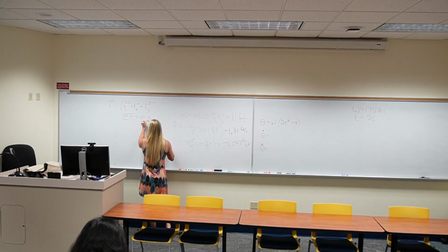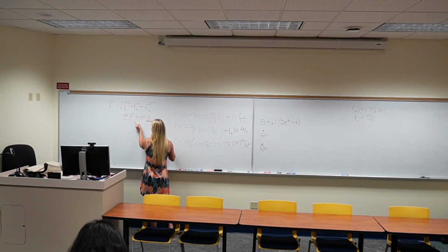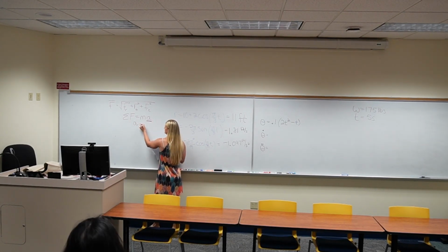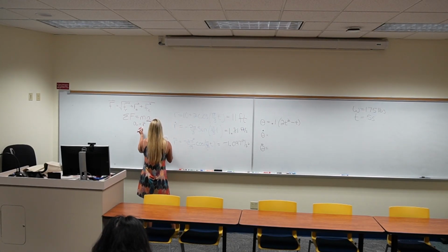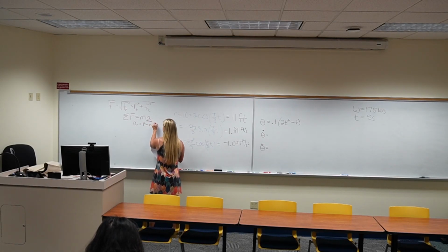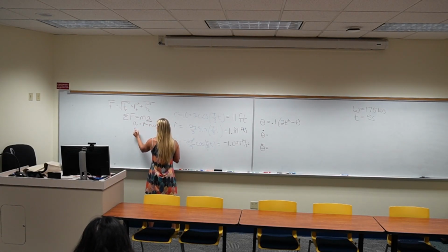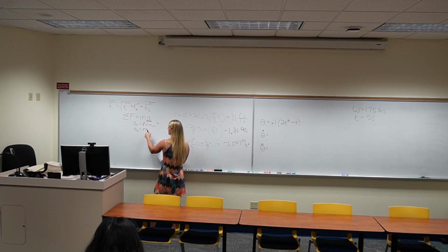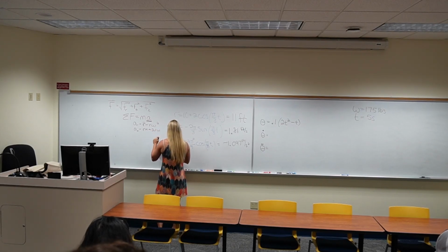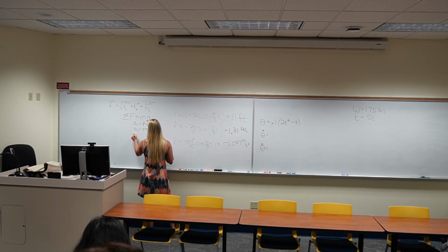If we are working in polar, what is A_r? Can you tell me what A_r is in your toolbox? It's r double dot minus r omega squared. What's A theta? Acceleration in the transverse: r alpha plus 2 r dot omega. And then what is A_z? Just A_z, yeah?